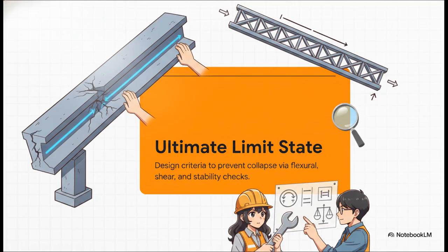A really fascinating detail here is that the pre-stressing process actually helps shear resistance, mostly because the compressive force it introduces delays that dangerous diagonal cracking.